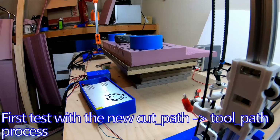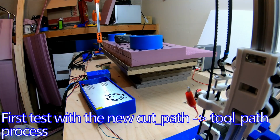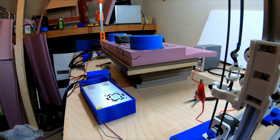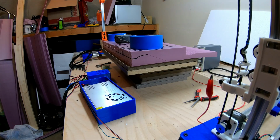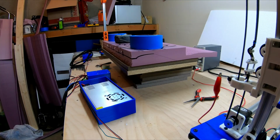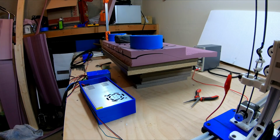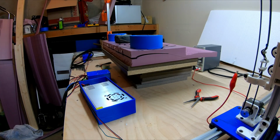So here's the first proper cut after getting all the cut path to tool path code working. And I ended up structuring cut paths in a way that you build up section after section in a way that they all connect together. And that way it's a bit more of an abstract way of forming the actual cut you want to do. And I ended up architecting it this way. That way whenever you get to the multiple subdivided cross sections, you just sort of add them together in a linear path to get the actual cut profile.